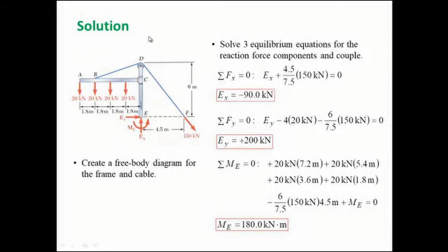So we will be able to treat that pulley as a particle and solve 2 reactions. We can find out that reaction, substitute here, then this reaction can be avoided. Instead, those 2 reactions can be substituted here, and also this tension has to be put here.